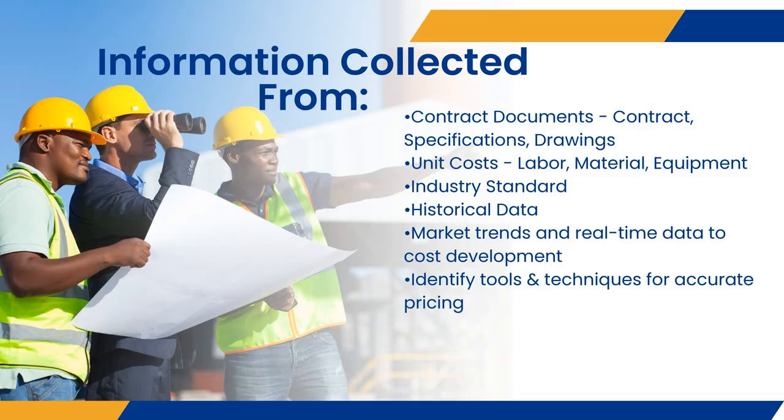This provides a very clear understanding to everyone in the room that on day one of the project, your plywood is always going to be $95 a sheet. Okay. So when tariffs hit us or when a material shortage hits us and we come in with a change order and we ask for plywood to be paid for at $145 per piece of plywood, our owner is not going to like that very much because the unit cost said at the very beginning that we were going to agree that it would never be more than $95.